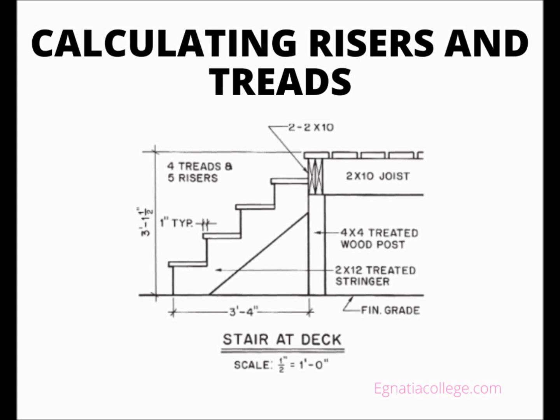The steepness of the stairs depends on the relationship between tread width and riser height. If the treads are wide and risers low, the stairs are gradual. If the treads are narrow and the risers high, the stairs are steep. To climb stairs with wide treads and high risers requires an uncomfortably long stride. To climb stairs with narrow treads and low risers requires an uncomfortably short stride. Building codes specify the maximum height of risers and depth of treads.